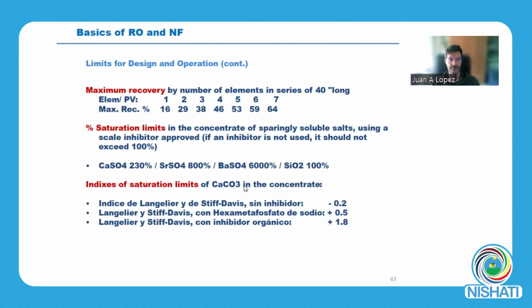Well, be very careful with the saturation limits of some salts in your solution that must be treated. Special caution with calcium sulfate, strontium sulfate, barium sulfate, and silica.